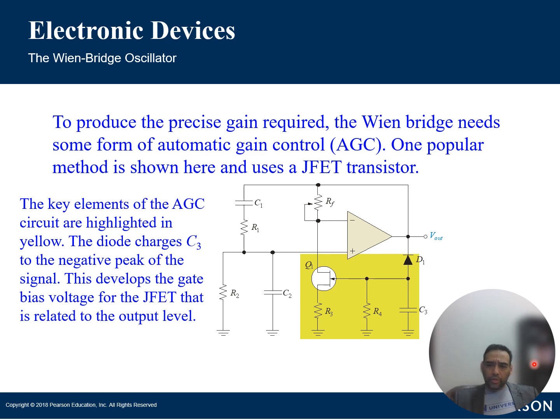Just got to pay attention to the component tolerances, because remember, we've talked about tolerances and components and their values and how they deviate when they're in different environments, right? So temperature being one of them. So the temperature stability of certain components will change the value of those components. And so a typical resistor with 20% variance, that's a lot of variance, right? If it's necessary for the stability of the oscillation. And I mean the frequency and the amplitude of that.